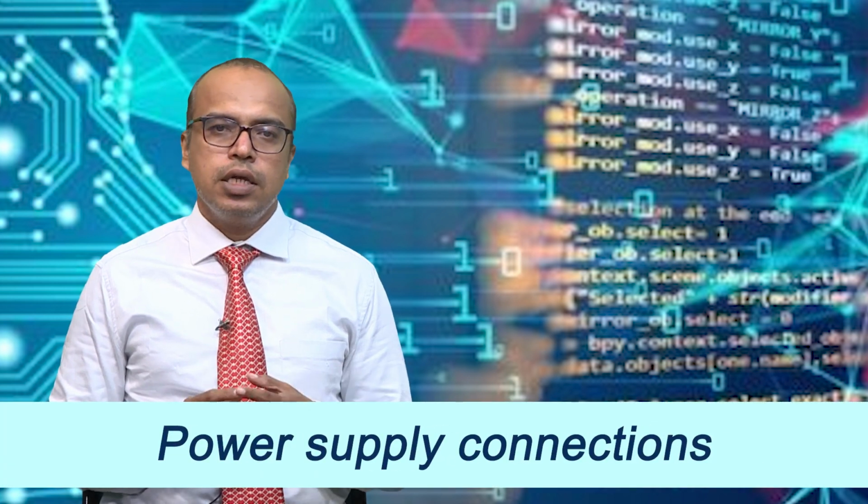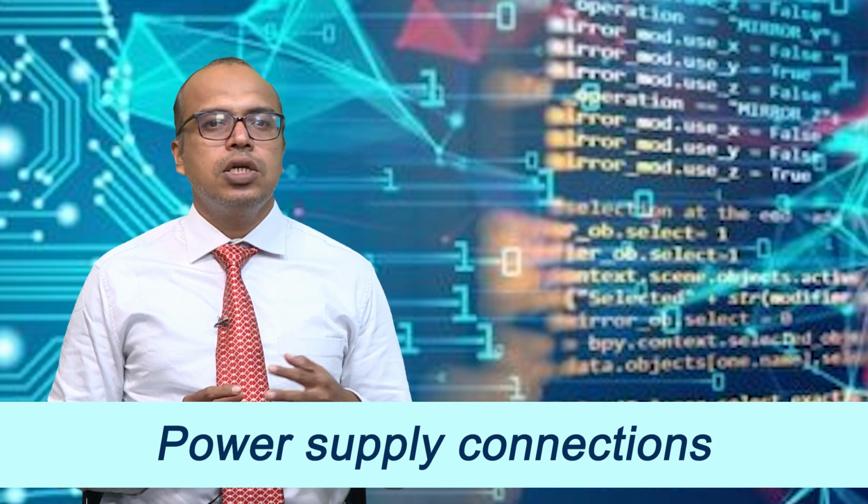Power supply connections: there will be connections for the power supply, often labeled VCC and ground. These connections provide the necessary biasing and voltage level for the transistors to operate. Feedback component is optional, it depends on you. Depending on the configuration and purpose of the differential amplifier, you might also see feedback components like capacitor or resistor for fine tuning the amplifier's characteristics.